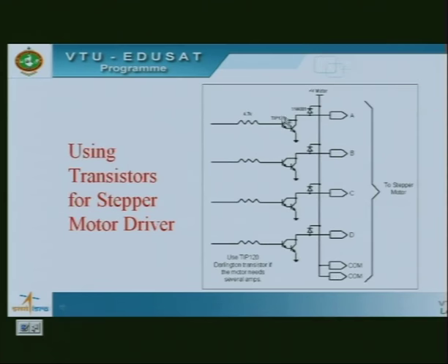You can see two transistors connected back to back like this will give a very high current gain, and it is used in common collector configuration. Remember, common collector configuration of transistors gives us the maximum current gain, but the voltage gain is 1. So there is no change in voltage, only the current will be increased. That is what we need here. The output voltage of the 8051 should remain the same, only the current level should be increased.